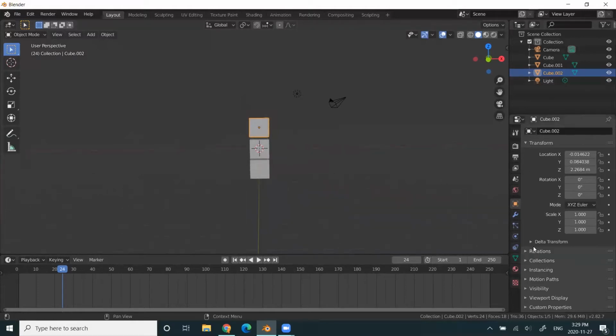Now here on the right side, if you go into this tab, which is your properties tab, you can open up this drop down, which is your transform. Every time you select whatever object, it will have its own translation values, rotational values and scale values. All we're going to do for the exploded view is animate the location values, or translation values, right?